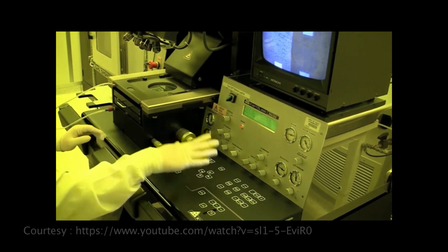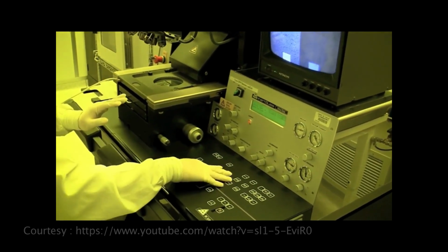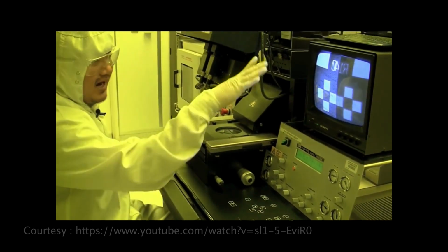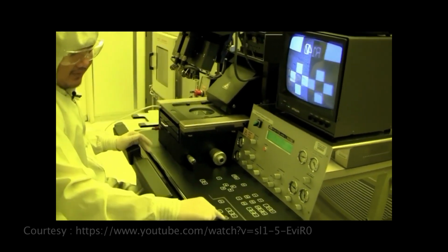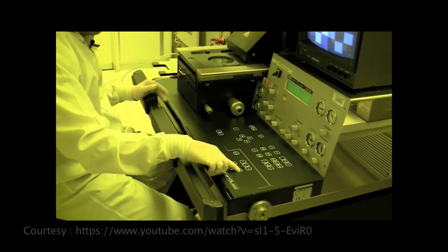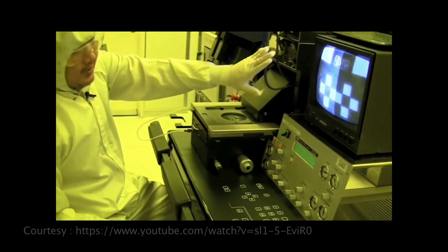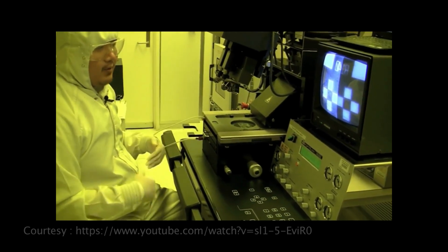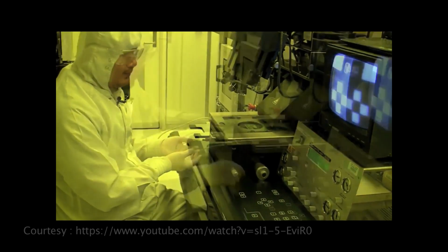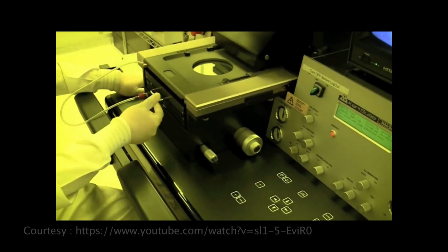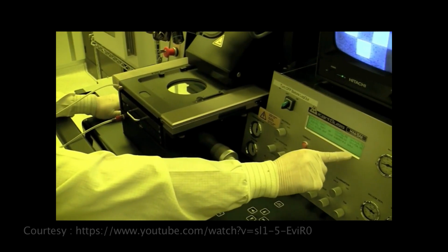So when you find your mask and you think you're ready to do exposure and align it, you would grab this image. So you press grab image button right here. And when you press that, what it does, it takes a picture of the mask. And now we're ready to load the wafer. We press this button where it says load wafer. So it says pull slide and substrate onto chuck.